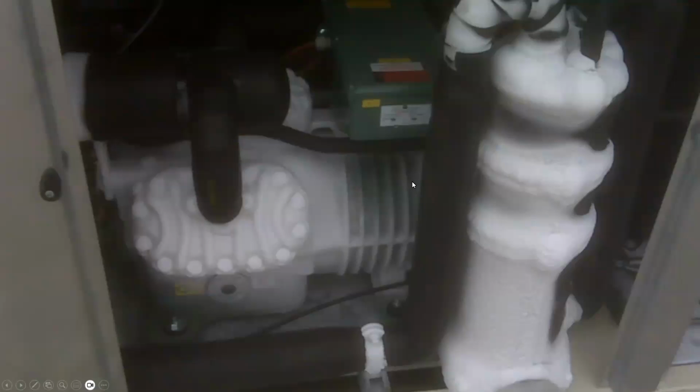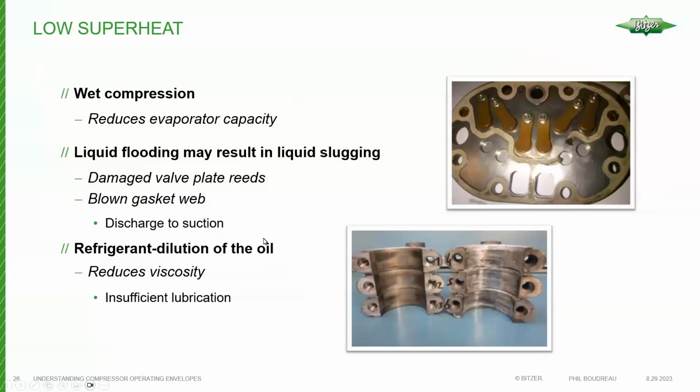But you never would see this. A frozen crankcase, frozen motor barrel, and discharge superheats are going to be very low. Lubrication will be very much compromised.